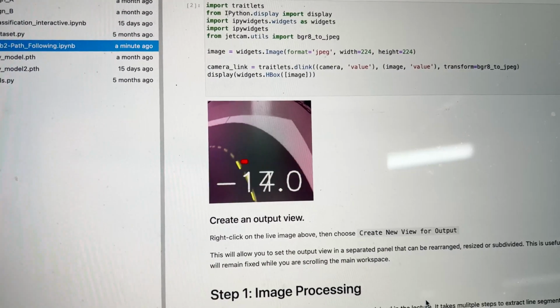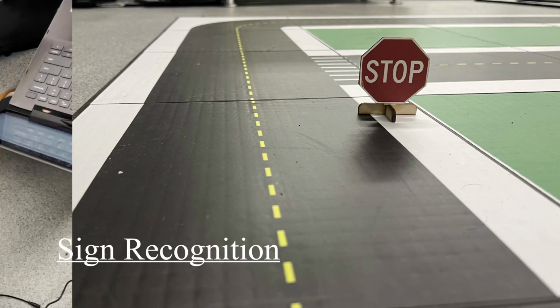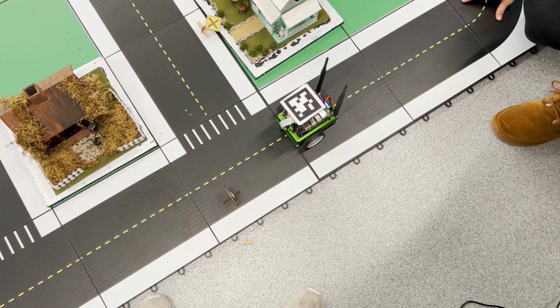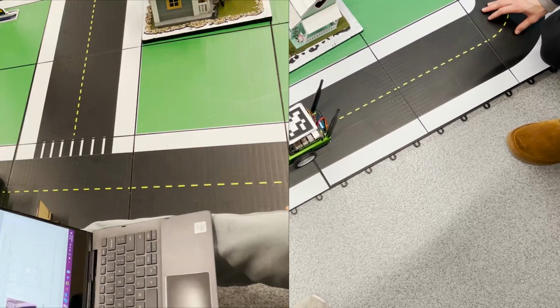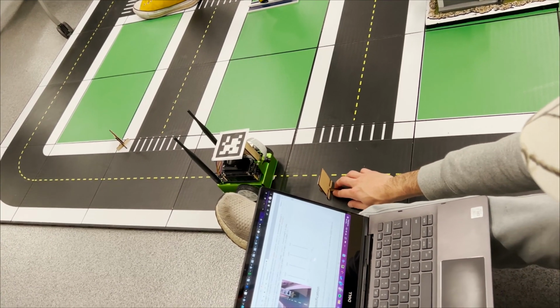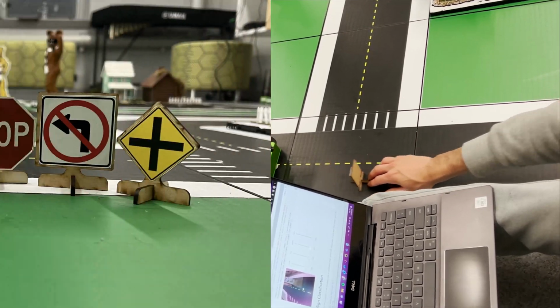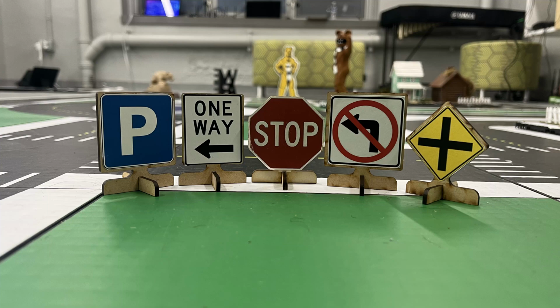The group began by taking several images of 3 different possibilities the robot could encounter: no sign, stop, and speed. These images were processed and a model was trained to allow the robot to recognize differences between these signs to account for the change in scenery. This model was then used with kinematics to allow the robot to move while there is no sign, to stop once there is a stop sign in view, and speed up when the speed sign, in this case a yellow sign, is seen. Lab 3 introduced a new perspective into a UAV track, overhead cameras with April tag processing.